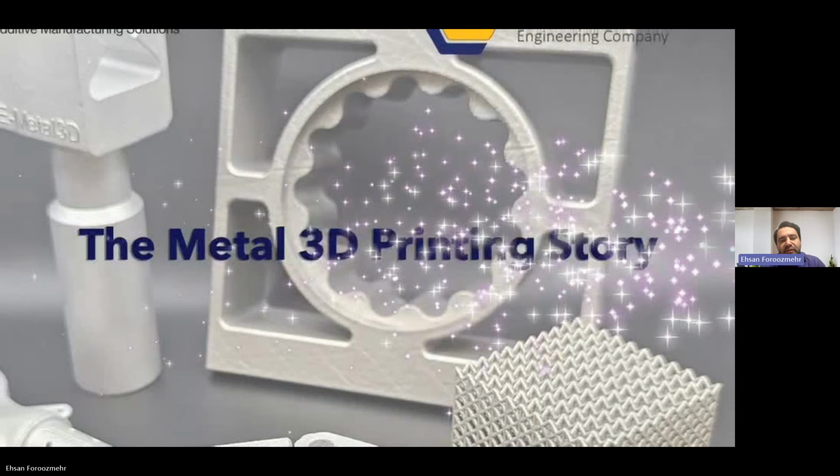While everything here is very automatic with no human involvement, the next stages are relatively labor intensive because you have to cut the parts from the platform. As you can see, this is the platform everything has been built on, and all the parts have to be cut from it and go to the next steps of post-processing. It can be some machining or deburring, cleaning the supports and so on. Sometimes you need to have some final inspection.